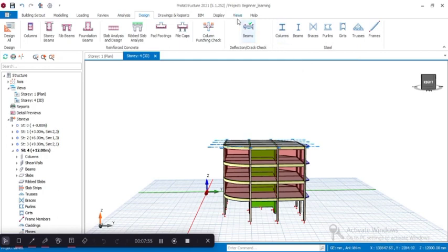So now for slab analysis and design. For beam slab models, slab reinforcements can be obtained by inserting slab strips in the x direction, horizontal plane, and y direction, vertical plane. This process uses the moment coefficient method from the tables in BS 8110.